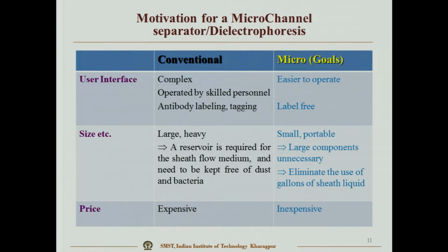Now, one of the physical processes is known as dielectrophoresis. We can utilize the electrical properties of the cell itself to separate the cells. I do not have to tag with the fluorescence labels. There is no need for the antibody antigen reaction, and you can do it without that. While in a microfluidic channel, the cells will move due to their electrical properties. In particular, the dielectric property of the cell can be utilized to separate the cells. Okay.